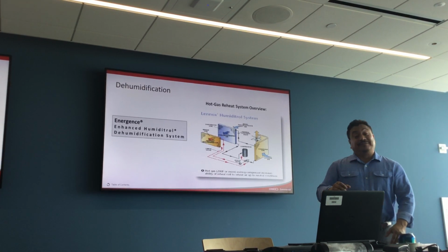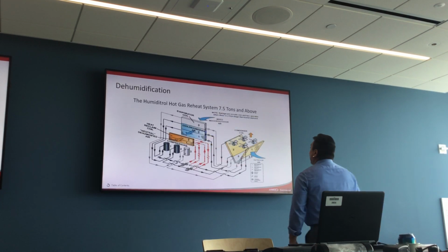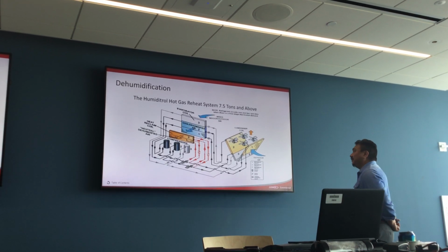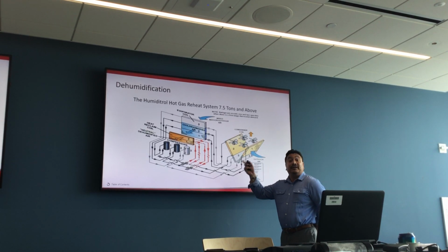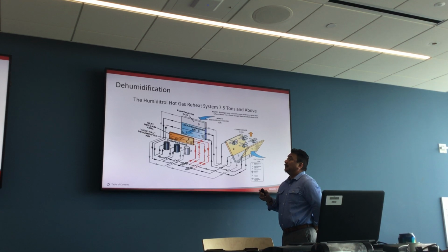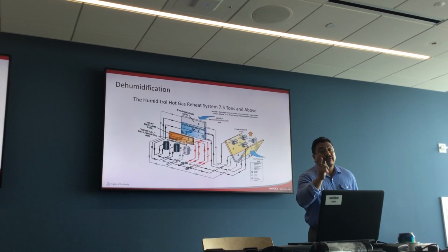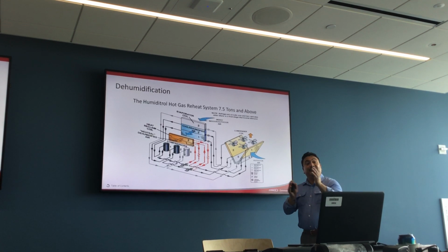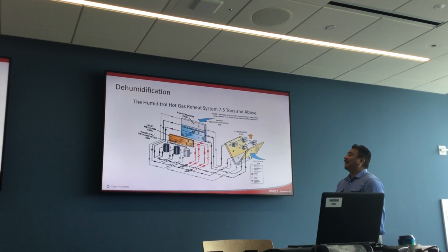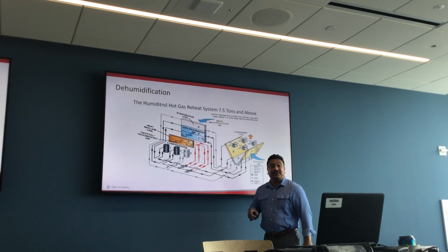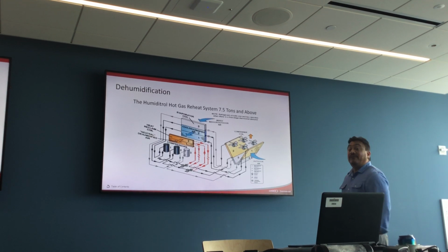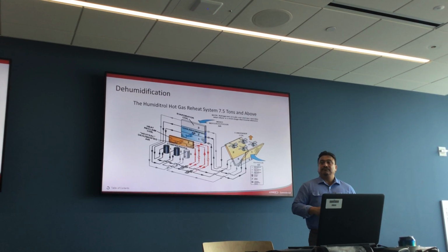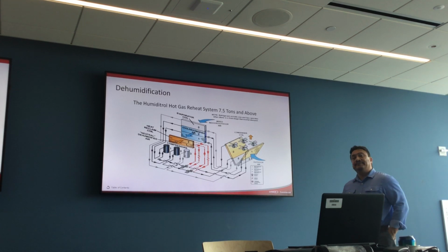Now, where this really gets complex is when you have multi-circuits. Look at that. Notice the difference in the coils, okay? Essentially on some units, you may have more than one evaporator coil, not necessarily in a stack configuration, but offset from each other, so there's layers. That really gets interesting when you get into the higher tonnages. Westlake's got the two big ones, 7.5 tons and above.